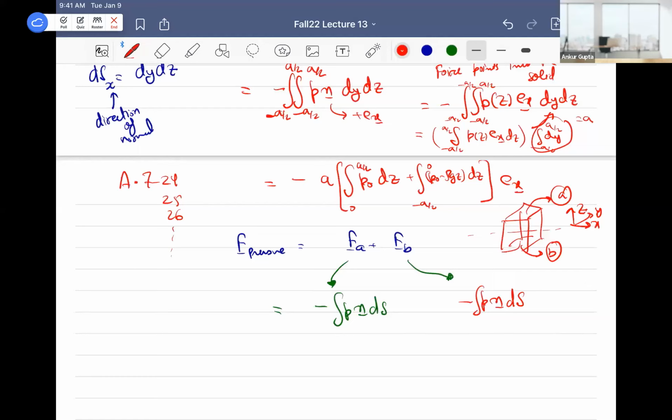So this was a question that a student asked me. I had never appreciated it. They said, well, I want to find the normal direction pointing into the direction of water. But remember that this block is actually in air. So the fluid is now the air. We cannot say the water fluid. The only interface is air-solid, so we cannot think of water anymore. So here we have to only point towards air.